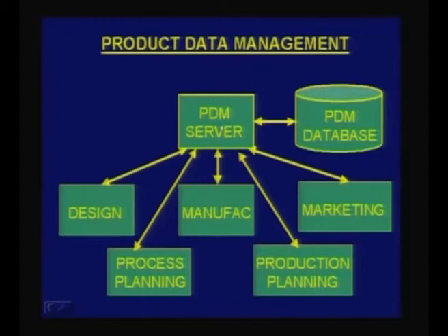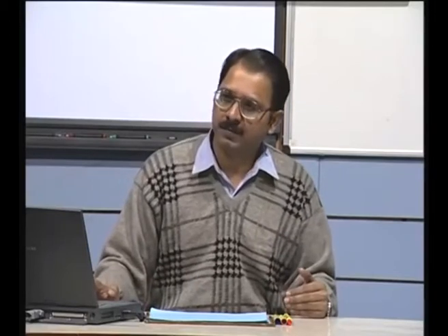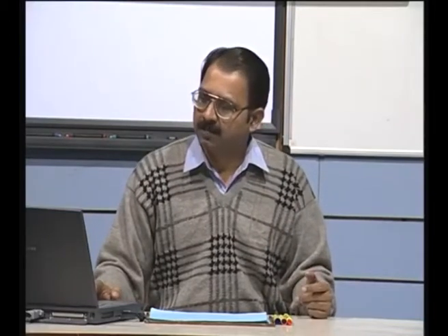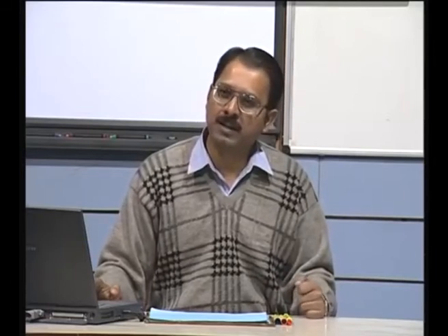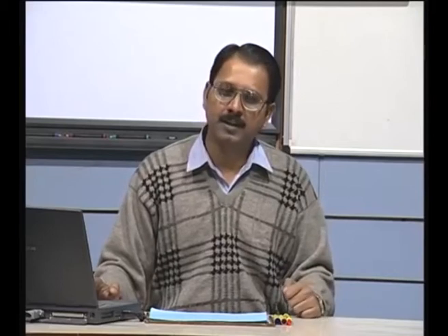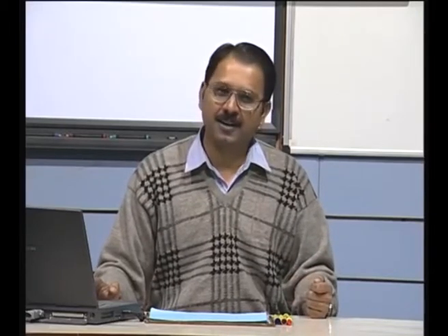Since product information is critical to many people, if everybody is modifying, they can always post it at a central place. So, this will have various versions. Suppose the design has undergone, let us say, 10 changes, from version 1, 2, 3, all the designs are stored. If somebody wants to refer to why this has happened and how it has happened, one can always take it back. PDM can store information in various ways. It can be a text file, an image, an IGES file, a STEP file, or it can be CL data, that is cutter location data, which has been generated as a part of a program.